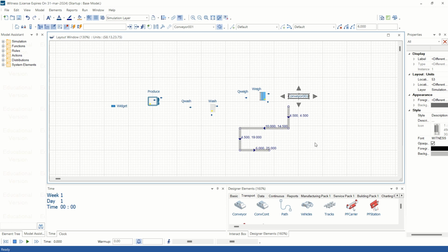This is your design of the conveyor, right? Then you have to click. You have to hold the shift button of the keyboard and click on this arrow. It will get converted into square. And again, click on this arrow by holding the shift button. It will convert into square. Then again, hold the control button and drag this part of this conveyor, right? So your conveyor is completed.